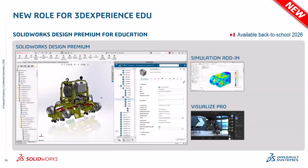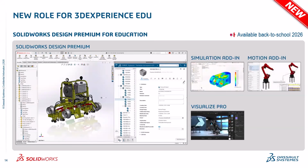But now it also includes the Simulation add-in, which lets you simulate product real-world performance using linear static analysis for parts and assemblies. It also includes the SOLIDWORKS Motion add-in, which lets you perform dynamic and kinematic analysis of 3D assemblies to calculate how mechanisms move and interact and perform under real-world forces before any prototypes are built.